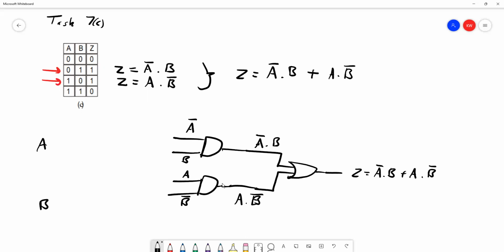So we now can connect some of these inputs directly to what we've got on the left-hand side, and some of them need to pass through a NOT gate first before we do so. One of those is the first input to the top AND gate. We have A bar, our input is A, so we need to put a NOT gate in here. So our A signal can pass through this NOT gate, and we can connect it up to the input to the AND gate. A passing through this NOT gate gives us A bar, which is what we require for the first input. We also need an A going into the bottom AND gate, and this time it's A without the bar. So we can take a connection from before where the NOT gate is and join this up to the second AND gate.